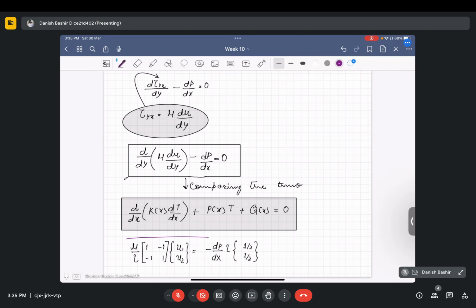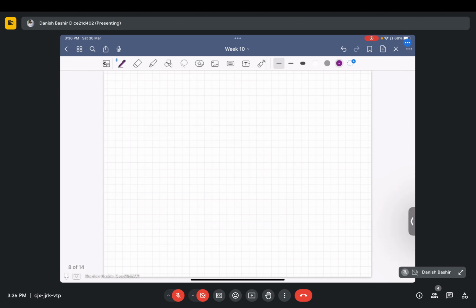This was very simple, very easy, because we had already deduced the governing differential equation and its solution. Once this velocity profile is known, we have the velocity at all the points. We can then easily compute the velocity pattern within the fluid depth, as well as the gradient of this velocity and the shear stress. The formulas for them are as follows; I will write them directly.